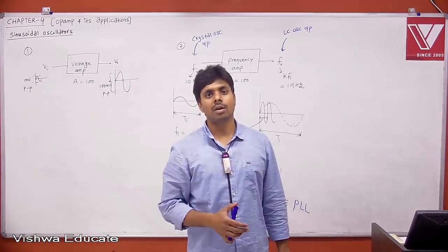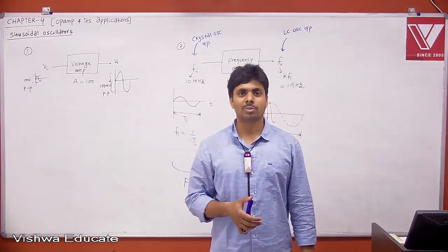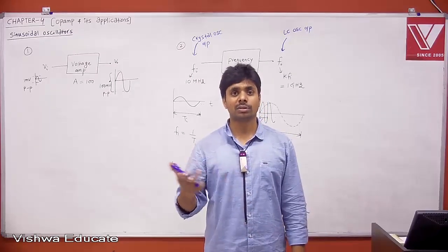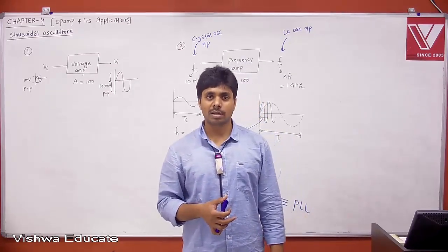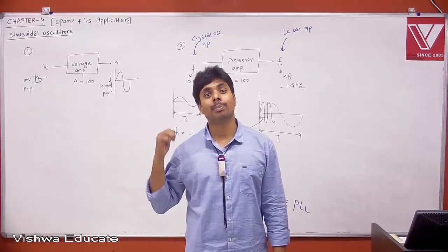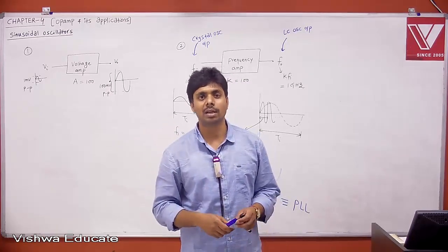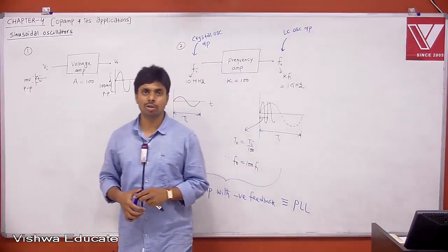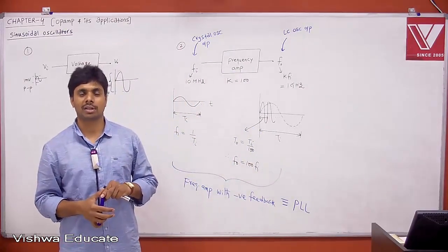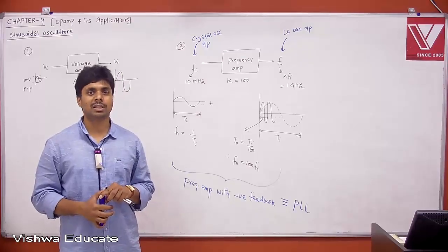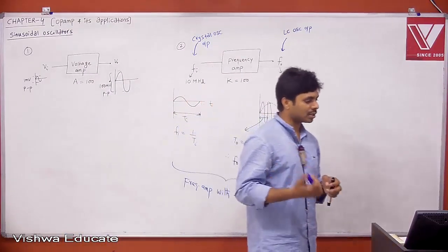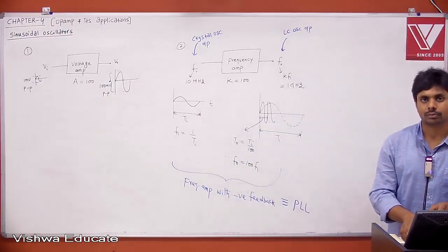When I say serial I/O, 5 Gbps of USB data, USB 3.0, remember the clock which we need to send the data of 5 Gbps is nothing but 2.5 GHz. From where are you getting that 2.5 GHz? We get it from a PLL. People practically use PLL, phase lock loop, which has two oscillator configurations. Number one, crystal oscillator. Number two, LC oscillator or Hartley-Colpitts oscillator. Okay, you take it, then I'll give you the PLL block diagram.